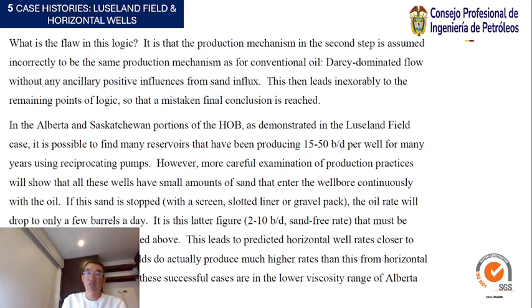However, more careful examination of production practices will show that all these wells have a small amount of sand that enters the wellbore continuously with the oil. If the sand is stopped with a screen, slotted liner, or gravel pack, the oil rate will drop to only a few barrels a day.